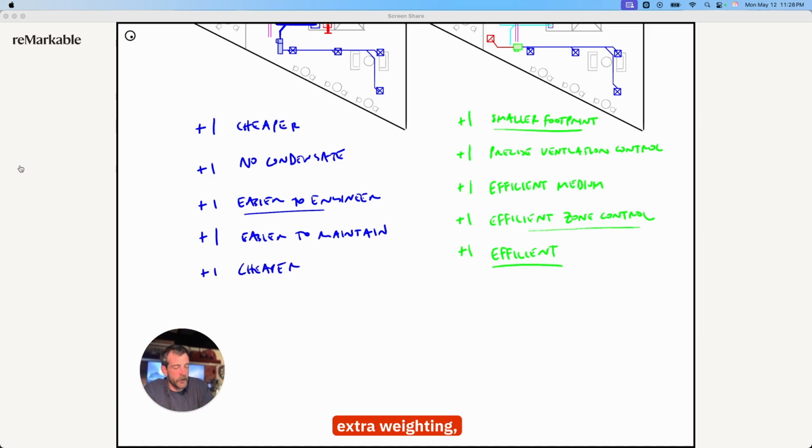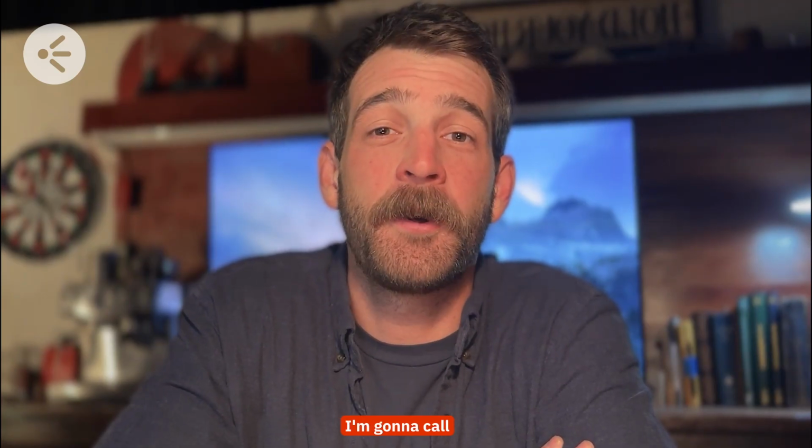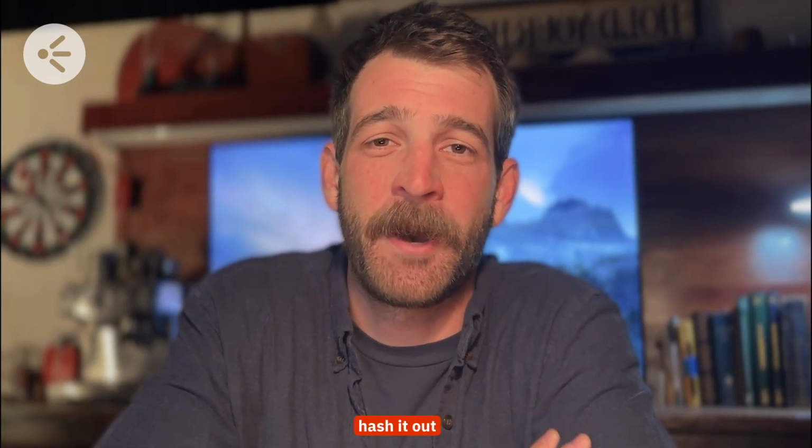And finally, just to even the playing field here, did I mention that VAV systems are cheaper? I think it's worth extra weighting because despite all the advantages of VRF, and yes, VRF is likely cheaper in the long run due to higher efficiency and lower operational costs, initial cost is still a huge factor. Because if you can't afford the thing, it doesn't get built. That's pros and cons of VAV versus VRF. I'm going to call it a tie, but I'll let you hash it out amongst yourselves.